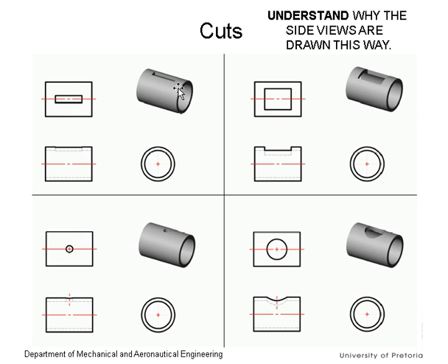The same applies for cuts. If you have a narrow groove into a component, from this view I won't really be able to see the vertical drop because this hole is now traveling down this arc. As the hole gets bigger, however, it moves further down the arc and then the vertical difference starts to become visible. So if it's a narrow groove, we don't mind if you just draw a straight line. As the groove gets wider, you'll have to start to draw what it would actually look like. The same applies to a circle.